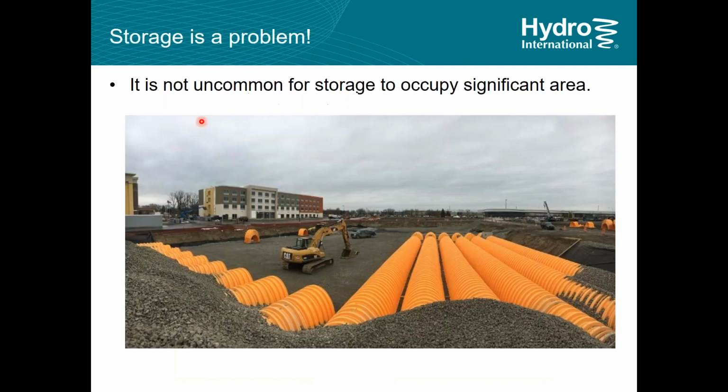You think that sounds ridiculous, but when I look at reality, we often see storage systems that encompass an entire site, almost an entire parking lot, that do go into these large volumes. Some of that is limited pipe depth or site depth, but other considerations are that it's very hard to limit the outflow with an orifice control if you try and put things deeper down, and as the poll said, the volume requires too much footprint.